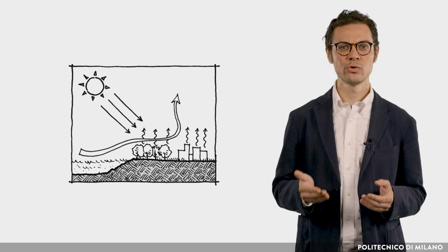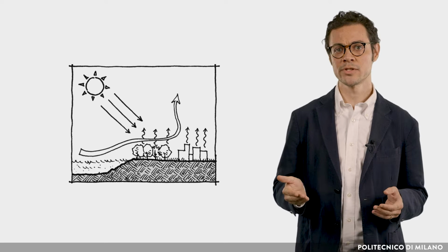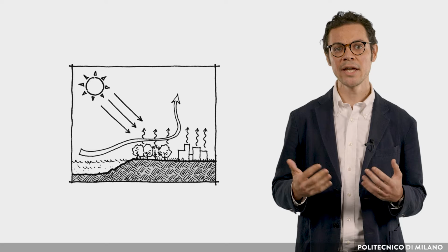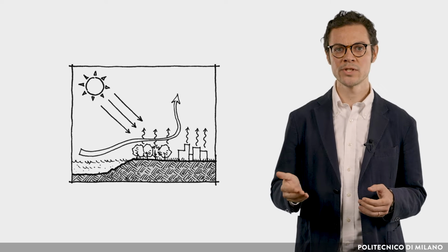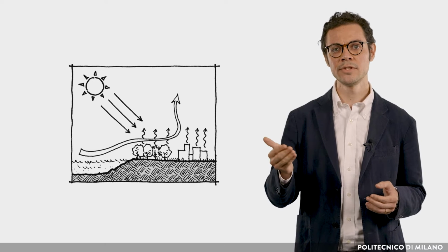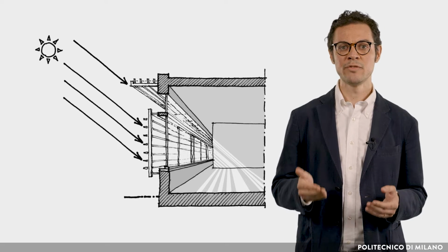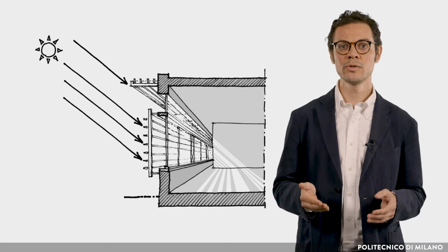Natural ventilation should be exploited as far as possible, so sites exposed to prevailing breeze are highly desirable. The closer the sea and the higher the ground, the more the breezes. In the building plan, it is pivotal to ensure suitable sun protection. For this reason, windows should be provided with shading devices.